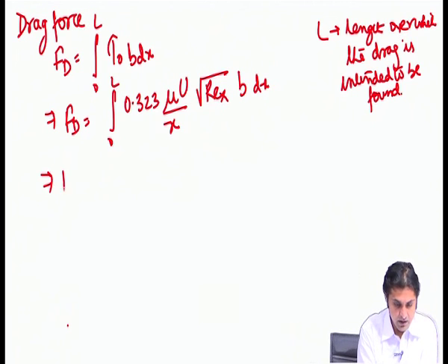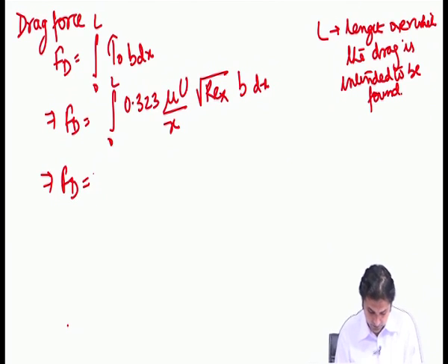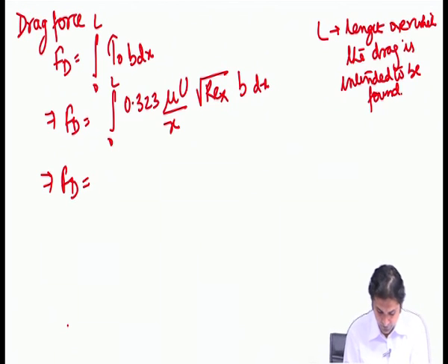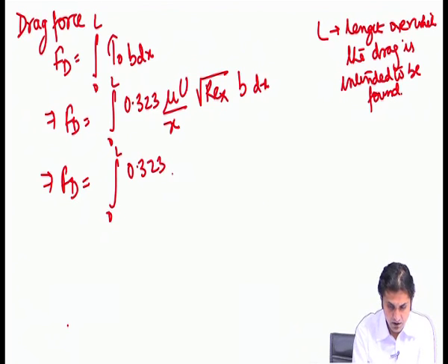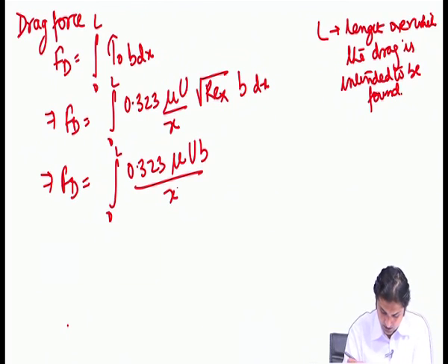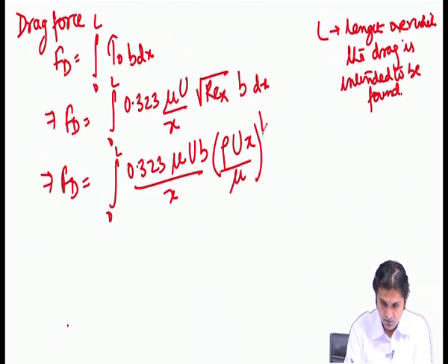So, this implies drag force is integral 0 to L 0.323 mu U b by x times rho U x by mu to the power half dx.